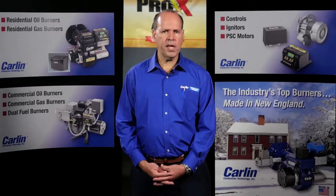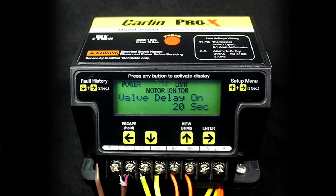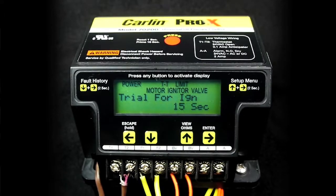On a call for heat, the screen will display the message pre-ignition for 3 seconds. The next message to appear will be valve delay on. If no valve was selected, then the sequence will advance. Otherwise, the message remains on the screen with the time indicator counting down. After valve delay on, we progress to trial for ignition.